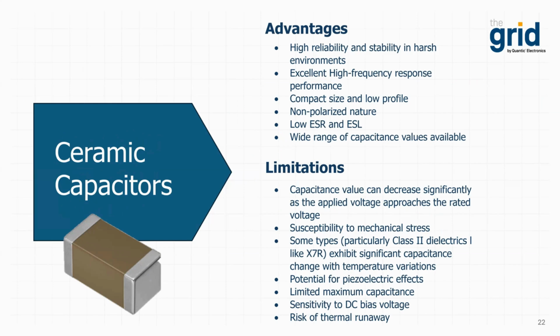Ceramic capacitors have a long legacy of use in avionics and typically are selected for their reliability, resistance to vibration and shock, and excellent high-frequency performance. Some notable advantages include high reliability and stability in harsh environments. Now, this makes them very well suited for extreme conditions typically encountered in aerospace.